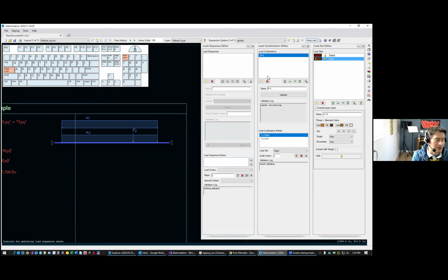And this is useful if, for example, you have a construction loading case where you want to make sure that, like in our case here, actually, we're going to have a composite beam. We'll want to know if the steel beam can support the wet concrete unshored before the studs that are part of the steel beam start to do their composite action with the deck. So that's one reason why we might want to run the loading in steps.